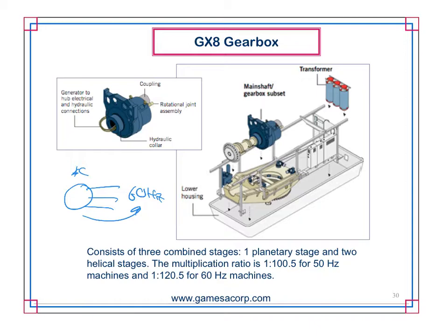If it's spinning at 15 RPM, that's slower spinning than what a hydro facility has. And hydro facilities need massively large units because of the torque. The power equals torque times omega. If you're trying to put out 5 megawatts and you're spinning at the equivalent of 15 RPM, you've got massive amounts of torque on that machine, okay?